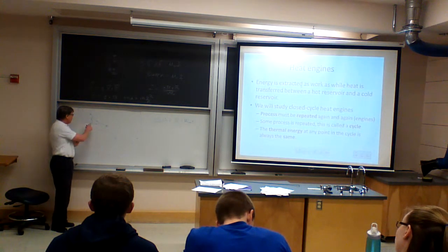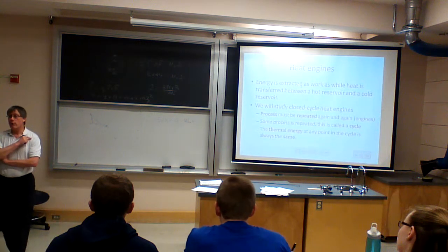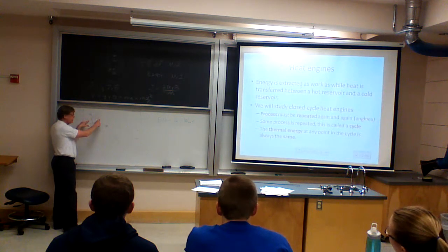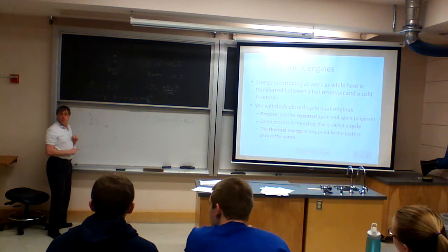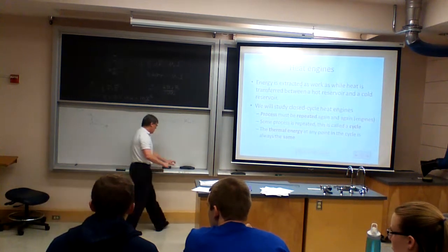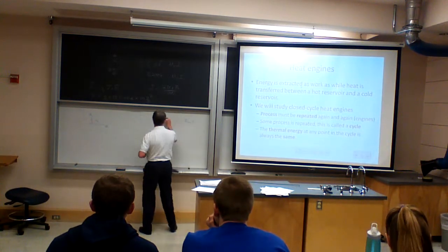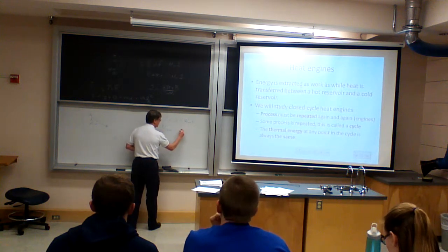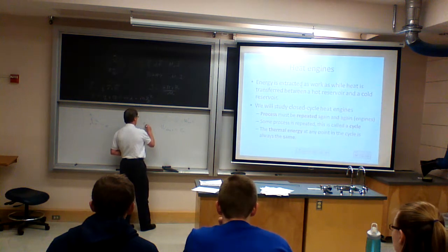Now, we're back to 1. What is our change in thermal energy over that entire cycle? If we add up the thermal energy here, plus here, plus here: 0. So if we look at this whole cycle, our equation becomes this. Or more interestingly, work out equals the Q for the cycle.